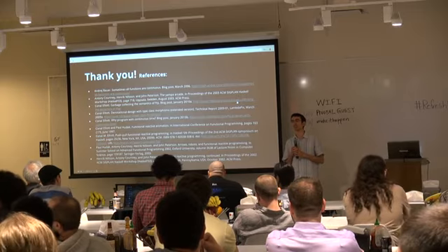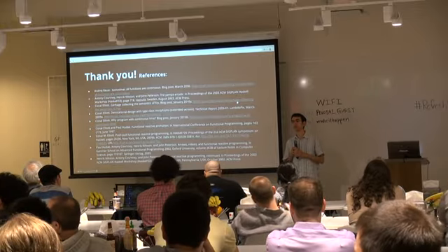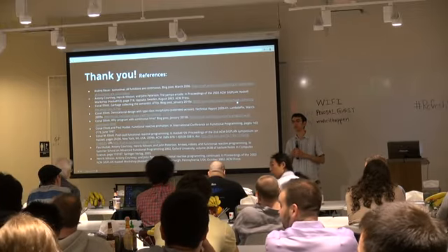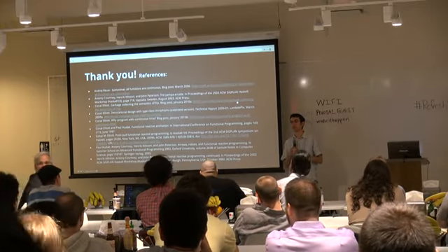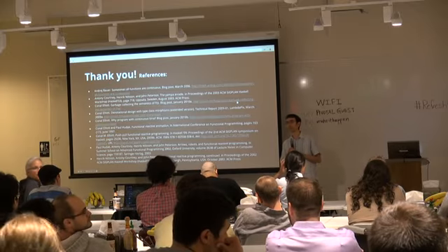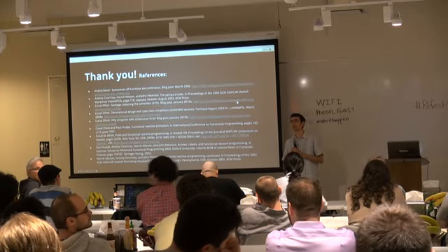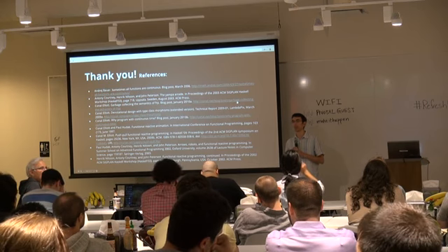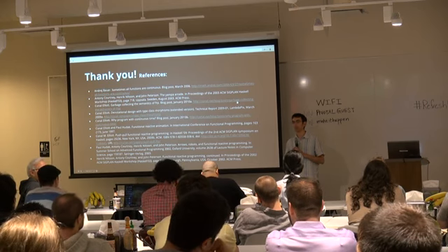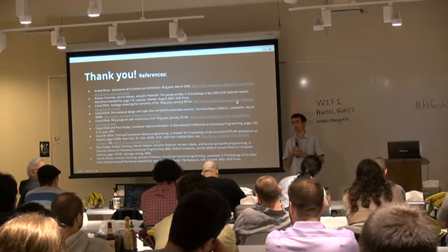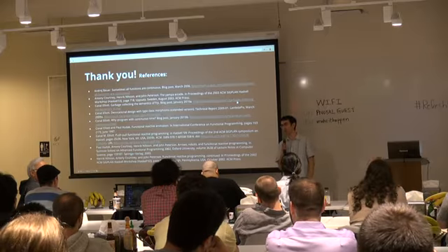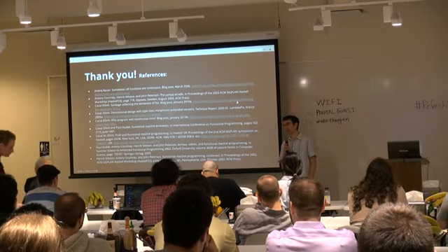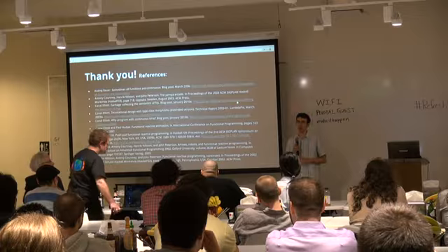Do you have any problems with Haskell's non-real-time nature interfacing with motors and stuff? Haskell has non-deterministic garbage collection, so sometimes it might take a few hundred milliseconds to garbage collect. Did you have any issues with that interfacing with robotics? No, and I think the reason may be related to what they say about arrows.